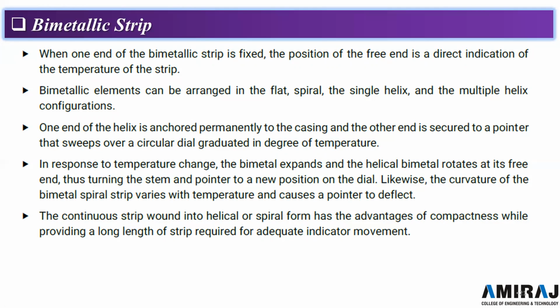In response to temperature change, the bimetallic element expands and the helical bimetal rotates at its free end, thus turning the stem and pointer to a new position on the dial. Likewise, the curvature of the bimetallic strip varies with the temperature and causes the pointer to deflect.